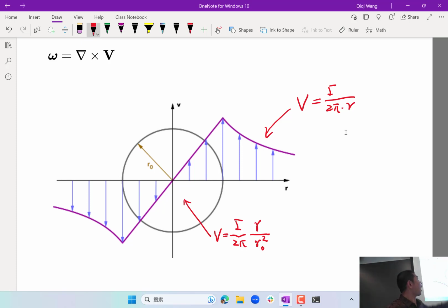Okay, so this is usually our mental model of what a vortex is like. In the very center of the core, the flow is rotational, outside is irrotational. Normally if you have a really viscous flow solution, the flow field is not ideal like that. There is usually a slow decay of vorticity at the edge of the core of the vortex, so maximum vorticity over here and decays to 0 over here. But mentally, this is a good idealization of what a vortex looks like.